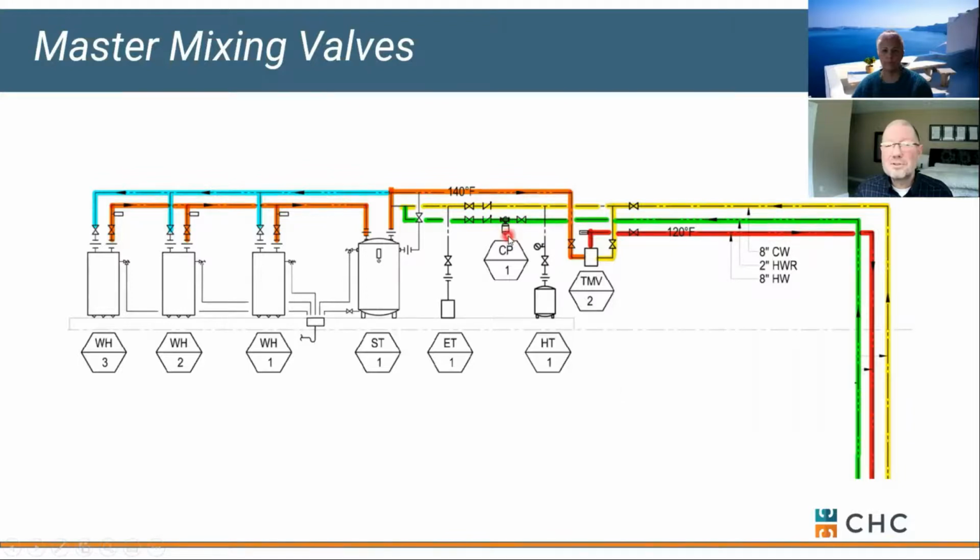So what do we do? We turn on a circ pump, and we circulate that line. So our recirc comes tight in here, picks up warm water from our storage tank, and serves the hot side of our tempering valve with the goal of sending tempered water down our riser to keep it warm. And it comes back cold. We pick up some heat, run it through our tempering valve, and down we go. Everything seems fine here until you realize, wait a minute, guys are waiting 10 minutes to get hot water in the morning. Maybe we're not keeping this tempered water line as warm as we should. What are we doing wrong?